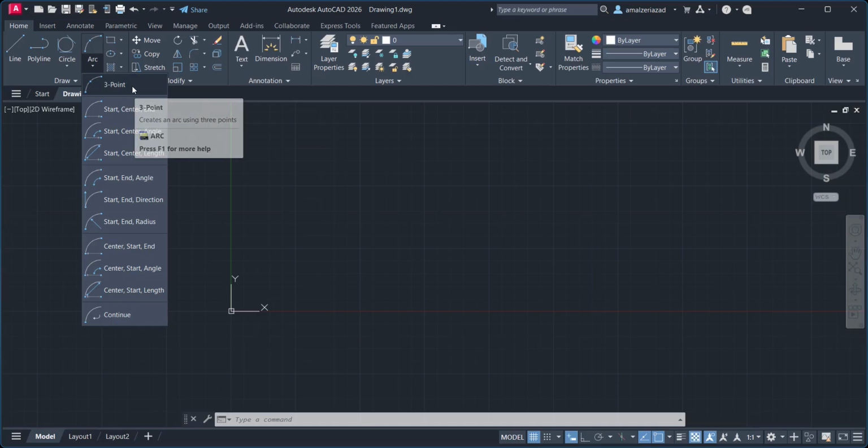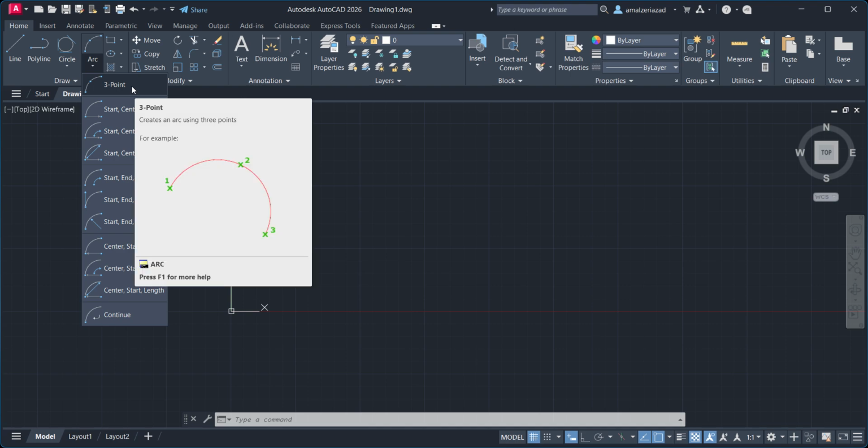So, this is the 3 point arc, which is not that much used. Suppose you have an arc. As I told, here you can't give the value directly; while creating it, you have to give the value. If you go for other software, the 3 point arc is the one which is maximum used, but here it is different.